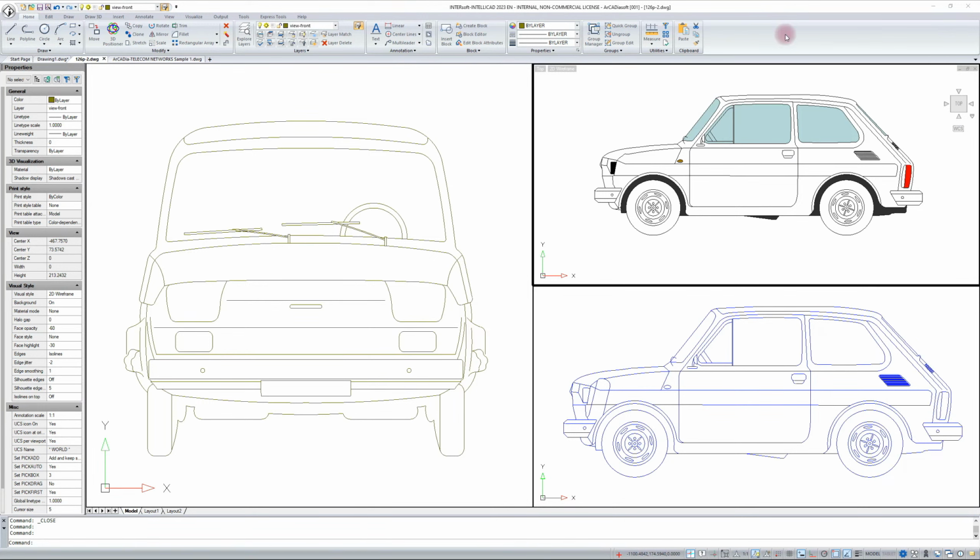Most of the things we're going to customize here today are on the Customize UI window. And we can get it regardless of our configuration, whether we have ribbons or whether we have toolbars. If we click somewhere beyond our toolbar icons on the ribbon, or here, past the File tabs with the right mouse button, from the menu we can access the various options, including Switch to Menu Bar, so that we don't have those ribbons at the top of the screen. If someone has a small resolution or prefers to work on toolbars, we can disable these toolbars for ourselves, and we can also minimize them.